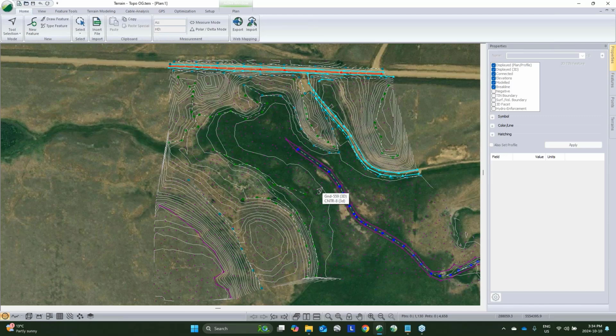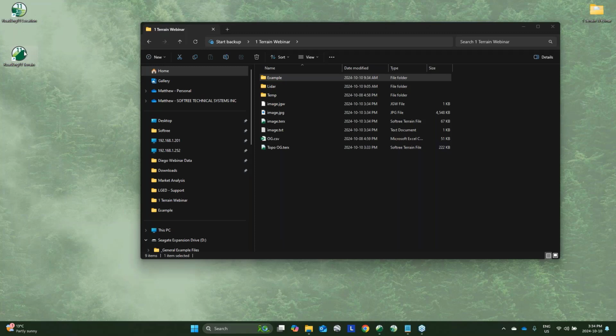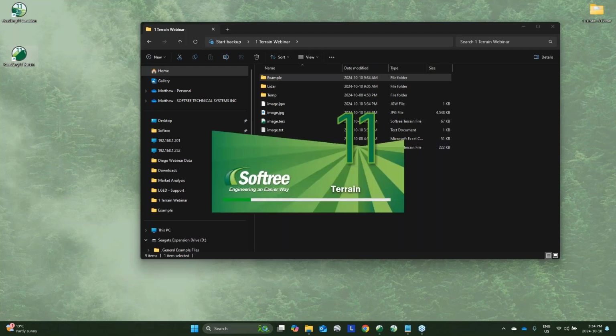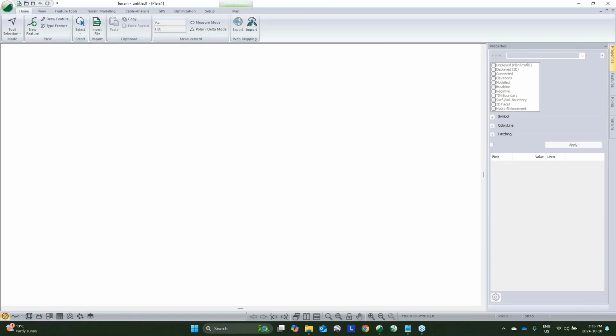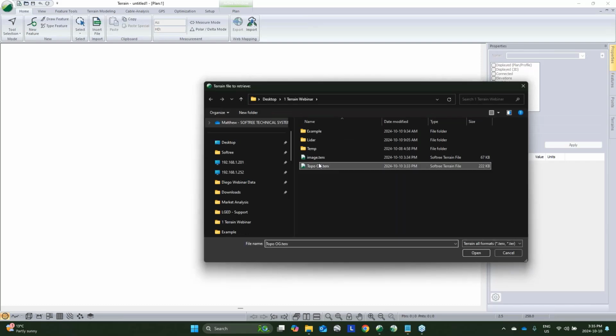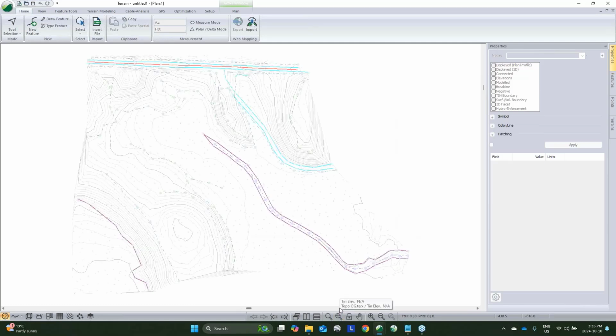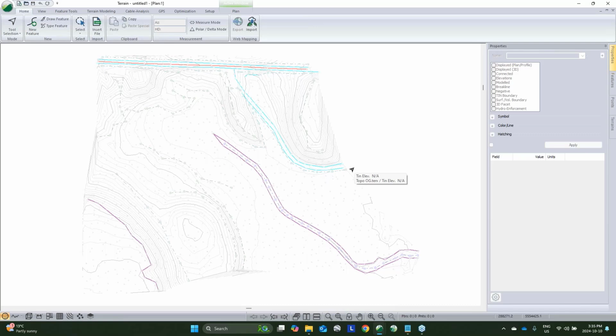The next thing that we're going to do is we're going to move on to using Train for design, and we'll get into that pond that Aaron introduced. So building on all the stuff that we've covered here, I'm opening a new Train. I'm going to right click, background, add. I'm going to add that original ground in as a background to this one. Great. Now, so that original ground has my topo surface, but I'd like to use this new Train file as my design surface.